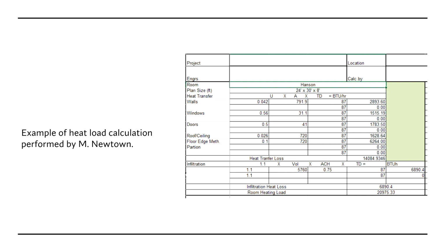And then we take a look at your leakage rate on the house, and the best way to do that is to have a blower door test done where we depressurize the house, and we can figure out where the air leaks are. Once we know that, we can give you an exact amount of air exchanges that should happen. And we'd really like to see an air exchange rate for a house of 0.2 to about 0.35.